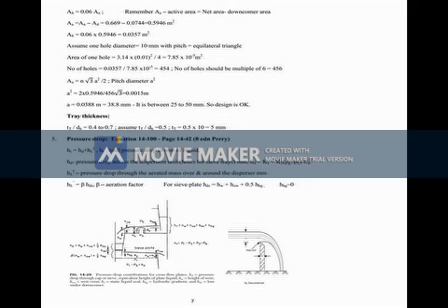So from this we get LS by GS is equal to 1.668. LS minimum is equal to 1.668 into 0.032, which is 0.0533 kilogram moles per second. But actually you have to take 1.5 times, so LS by GS into 1.5 gives 2.5017. This is the actual amount of liquid required, and this is the slope of the actual operating line, 2.51.